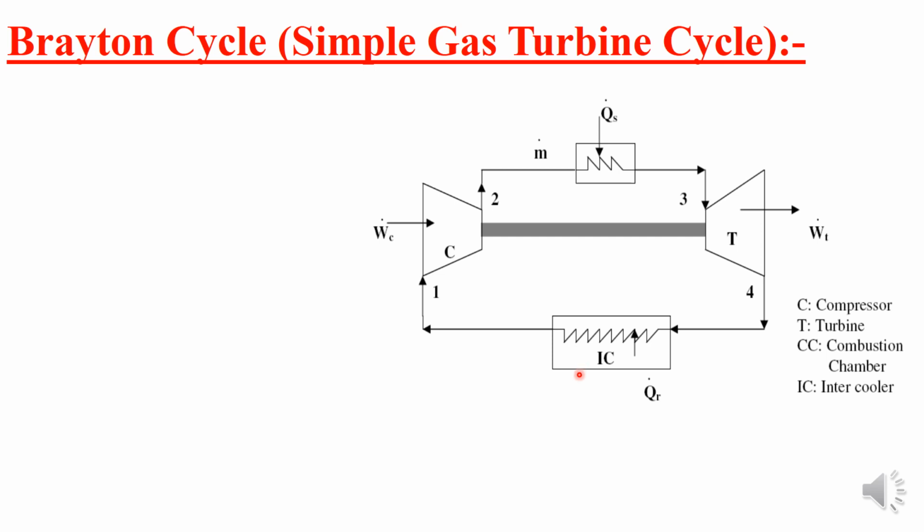It's similar to your vapor power cycle which you studied in the class. So it will enter into state 4 and it will reject the heat. So Q will be rejected to the surrounding from the system. This process, once again, is a constant pressure process. At constant pressure it will reject the heat. So it will bring the working fluid back to the initial condition, that is the P1 T1 condition.